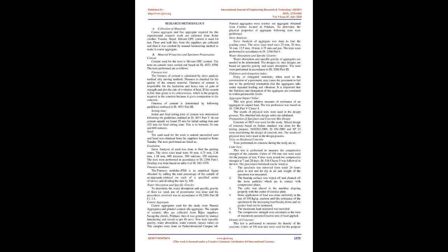1. Comparison of compressive and split tensile strength of concrete by destructive and non-destructive tests, i.e. cube test and rebound hammer test respectively. 2. Economic feasibility study of using waste ceramic tile aggregate as partial replacement of coarse aggregate in concrete production. 3. Comparison between combined flakiness and elongation index, mechanical properties, aggregate crushing value, aggregate impact value, aggregate abrasion value of waste ceramic tile aggregate, CTA, and natural coarse aggregate, NCA. 4. Comparison between specific gravity and water absorption value of different proportions of waste ceramic tile aggregate mix.